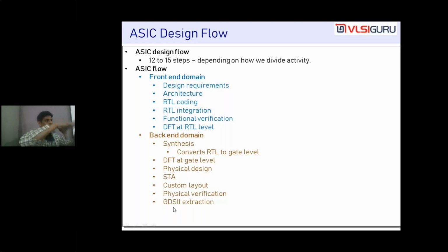Once they have come up with the entire plan, once they have drawn everything, they extract some file called as GDS2. Like what is the file name that you play songs and movies? MP4 or MP3, MP4, right? Like that. For chips, there is a format called as GDS2, like .c, .c++. The format of that file itself is called as GDS2. GDS2 will tell where should be the doping, where should be the metal, where should be the polysilicon. Like that, it will tell you everything in a three-dimensional manner. That file is given to whom? Foundries. What are the 2-3 major foundries in the world?